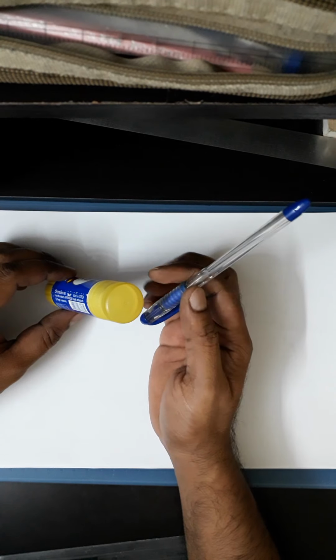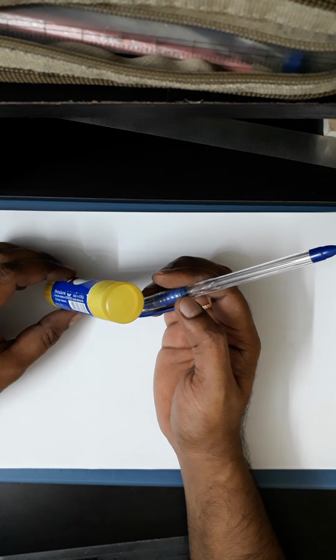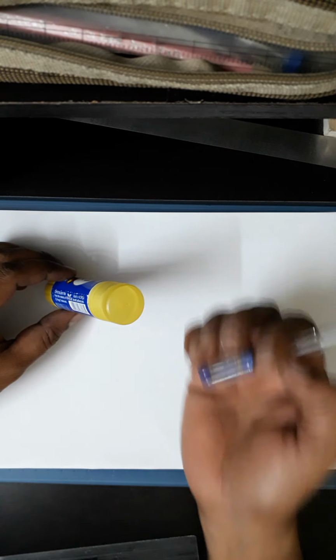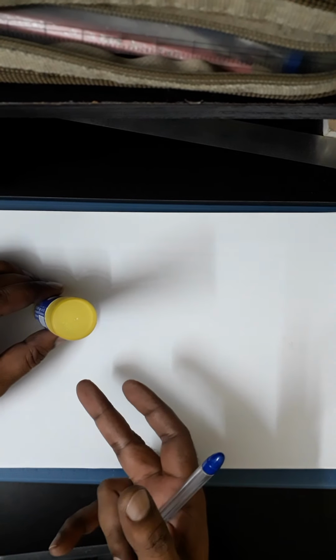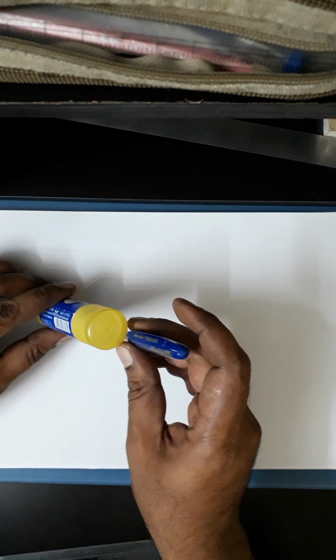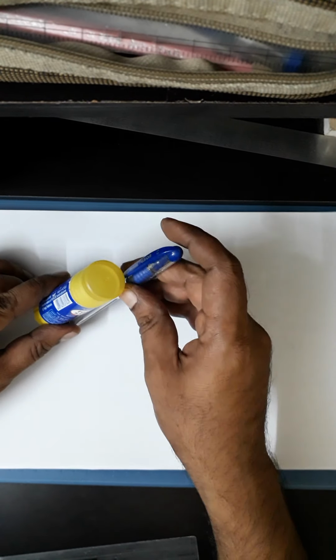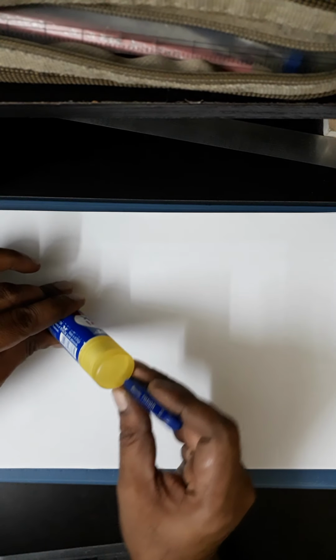Now the first problem they can give you will be axis inclined to both the planes. In that case, they'll say a cylinder of diameter, say, 50 mm and a height of 80 mm is resting on one of the points on the circumference of its base, such that the axis is inclined at 30 degrees to HP and 45 degrees to VP. Either this way or this way you can rotate. So for that you will go in 3 steps.